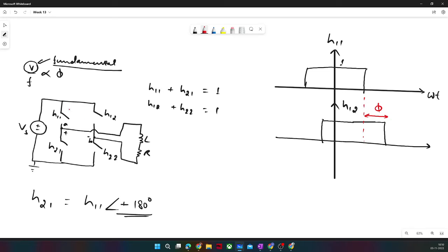Generally, what we have seen in three-phase inverters is that this was usually B phase, and this B phase was shifted by 120 degree to make the load balanced. But here we have single phase, so we do not have such a constraint, and we can generate our desirable pulse in whatever manner we desire.